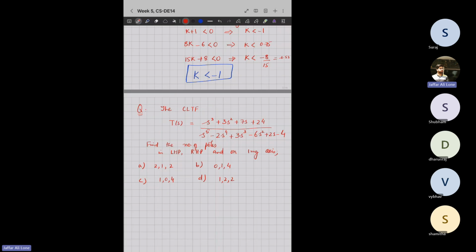You can decide one thing from the options. Imagine this one is imaginary, imaginary, imaginary, imaginary. So definitely there are imaginary poles, because all the imaginary options are present. When there are imaginary poles, it means there is a presence of a row of zeros in the RH array.